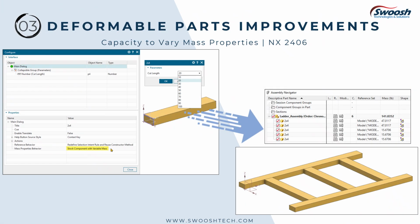Starting in NX 2406, you can now specify whether a deformable component uses a fixed mass or a stock component with variable mass. The original intent for a deformable component was to model parts that were manufactured in specific shape, but then stretched, bent, or otherwise deformed into position within the context of the assembly while maintaining the fixed mass properties. The mass in the original part and the installed deformed component would be the same.